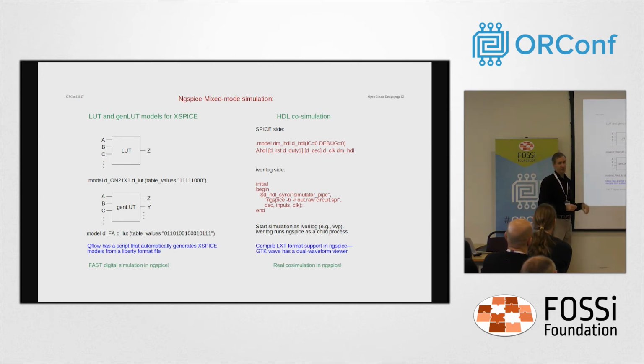One of them is there has been for a long time this feature called XSpice within NGSpice and Berkeley Spice. It was developed at Georgia Tech. And it's basically a digital co-simulator inside Spice. Its drawback is that it has fairly limited support. They had a few models that people made, and then beyond that, they stuffed it into the Spice source, and I haven't ever seen any more development on those models. They said, okay, you can just write your models in C. I don't know anybody who knows how to do that, really. I spent a bit of time learning. I just barely learned how to do it, just enough to do this, which was useful. So I generated 2 new models for XSpice.